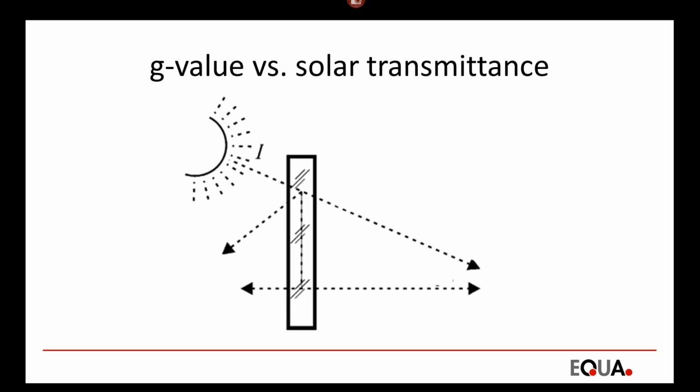And once this is radiation, it will heat up the constructions instead of the air. From here you can see quite easily that you have a single equation and two unknowns: the reflectance back to outside, and the part of the absorbance which is going outside as convection and thermal radiation. So this kind of standard window model you shouldn't use once you have, for example, a double skin facade, because the information on how to divide the reflectance and absorbance back to outside is not known.